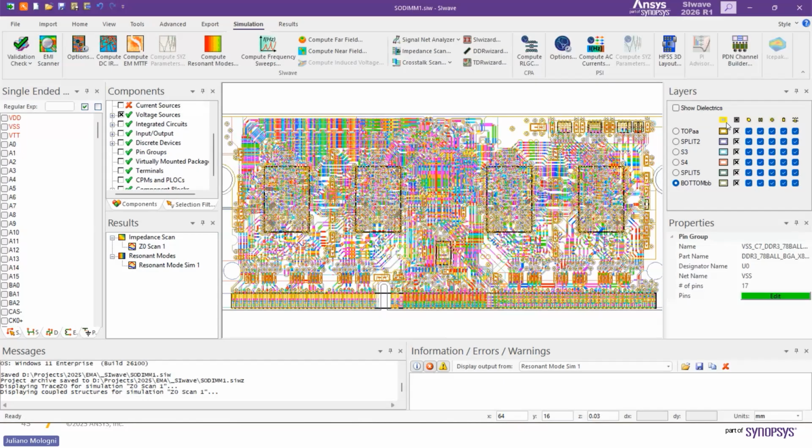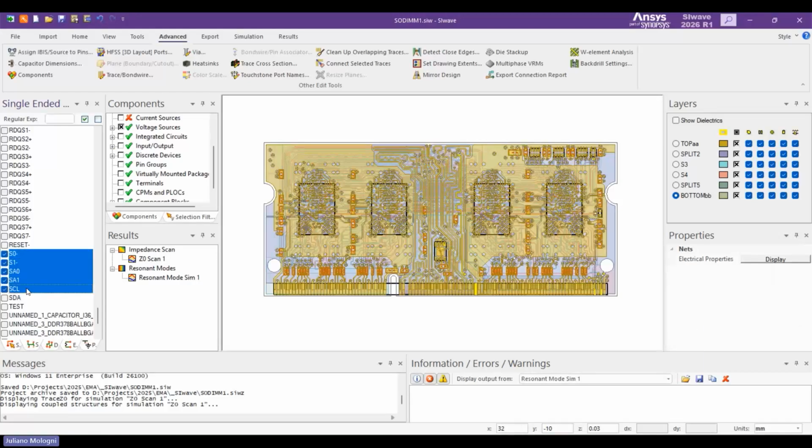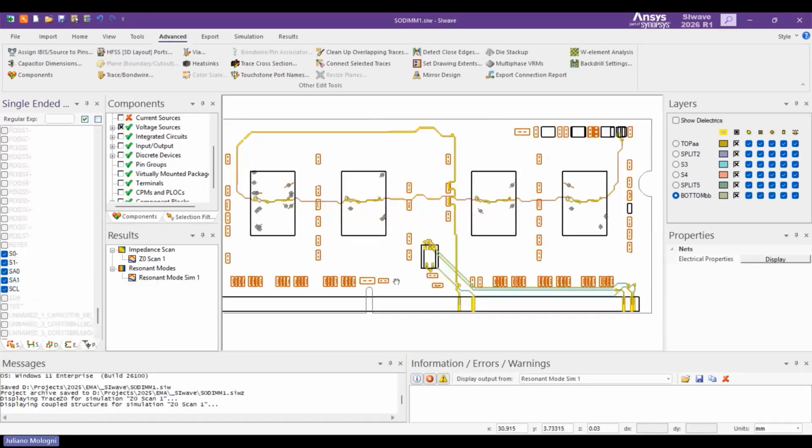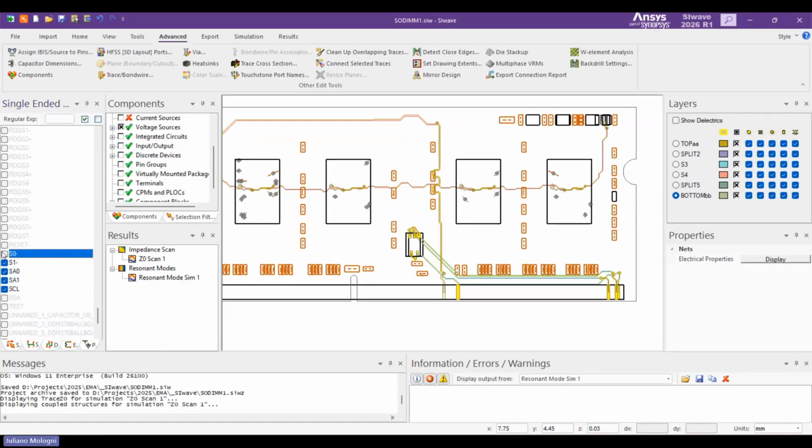So, I know most PCB designers are calculating, or you have that in the tool already, right? In any EDA tool, you specify the width of your trace based on your dielectric and your stack up, right? But sometimes you might have some surprises. You might want to scan the entire board, right? Another thing you can do is simulate crosstalk, in frequency and time domain. So that's also a really quick simulation.